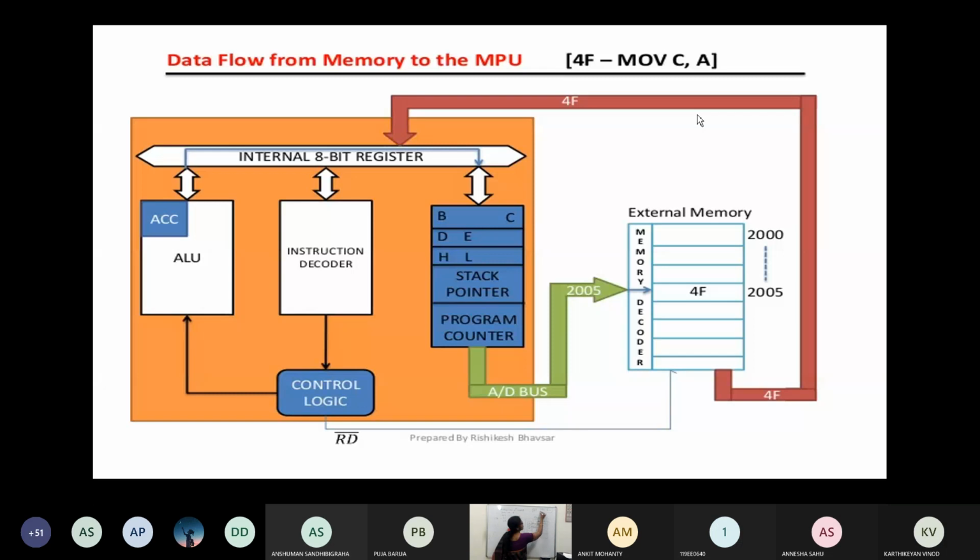Okay, hold on. This particular instruction won't be stored like that. It will be stored in the form of opcode. This is called opcode. I told you earlier itself, the assembly language instructions are already framed as opcodes and registered already. Right? So, for example, if this one is having 4F, what does it mean? This 4F will be transferred onto the data bus. Data bus is having 8 bits only. It is very well known. So, that will be coming here and go to the instruction register.